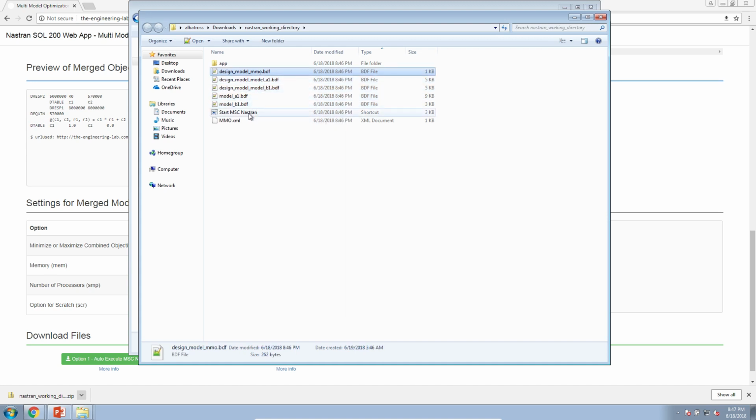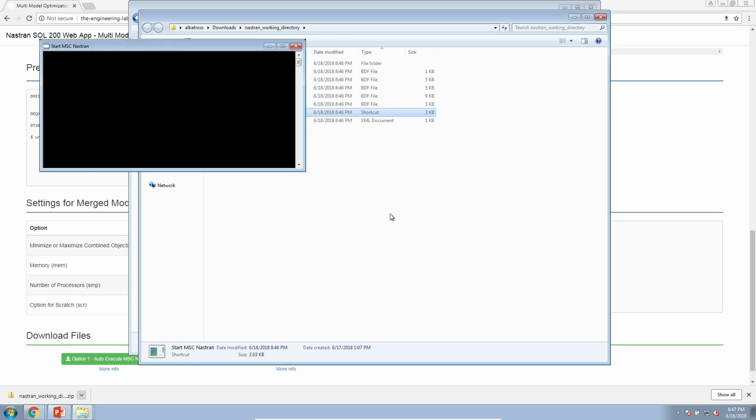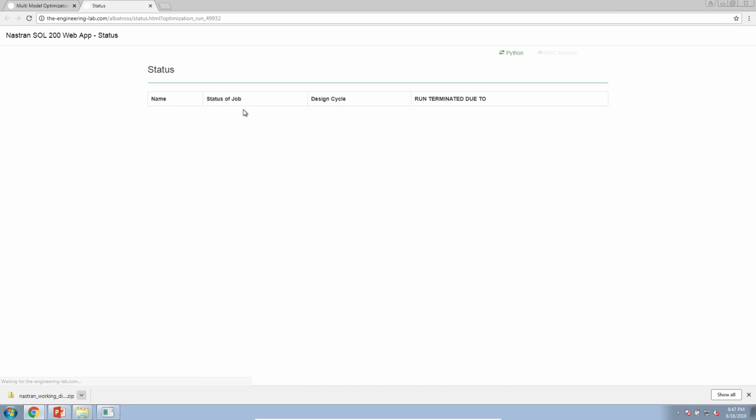You'll also see a few additional files. I won't cover that in this video, but at this point, just to keep the video short, let's go ahead and start the optimization with Nastran. So I'll double click on the start MSC Nastran, click open. The status page opens. Keep and pay attention to the rows that are coming up. Remember, we have 2 rows or 2 models. These 2 models will be optimized simultaneously. Multimodal optimization is happening. You notice that the design cycles are counting up simultaneously.